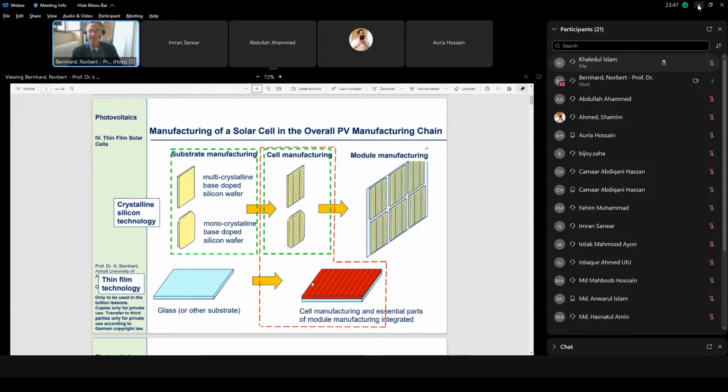Then here we have the p-doped cadmium telluride. I said already, no extrinsic doping is necessary. This is an intrinsic doping, which is just created by a certain non-stoichiometry of this material. And here we have the cadmium sulfide. What we see is that the cadmium sulfide has a bigger band gap than the cadmium telluride. Cadmium telluride has 1.54, which is near to the ideal band gap of a photovoltaic material.